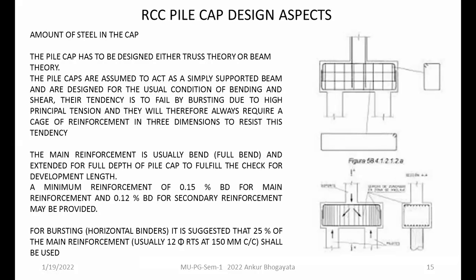Now, there is one more important aspect regarding the steel in the pile cap. I have already specified that the pile cap requires steel in all directions. So you will see some images on this side that it's just like a box of steel, right? When you create a pile cap, and when you calculate and tie up the reinforcement, it will start looking like a box of steel bars, right? But it is necessary, and do not avoid any direction where you don't provide steel. So in all directions you should provide steel.